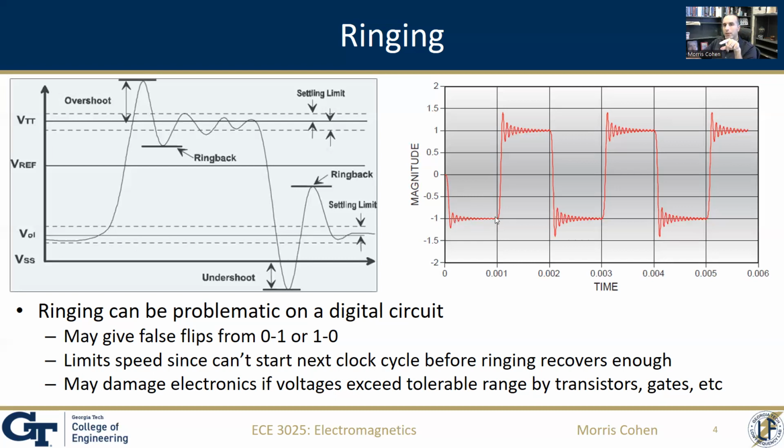Eventually, when the flip comes back to the positive side, it reverses, but again, you get this overshoot and oscillation back and forth before it settles out. So this is a known phenomenon. It's called ringing. And perhaps when you saw it at the time, you kind of waved your hand and said, whatever, bad oscilloscope, weird components, and waved it off.